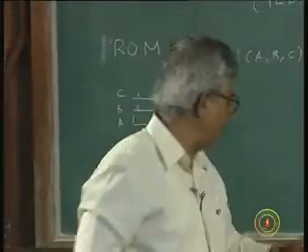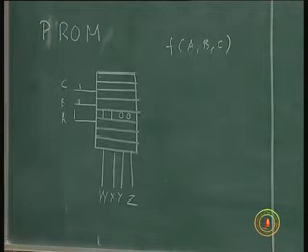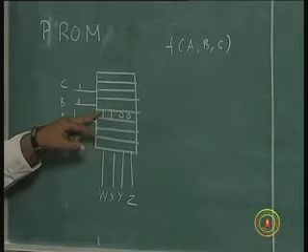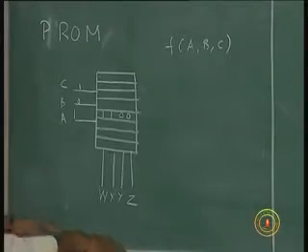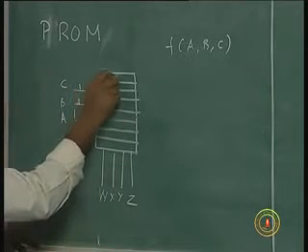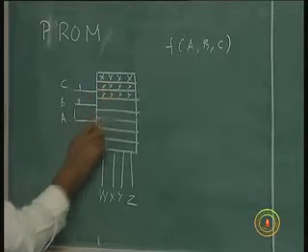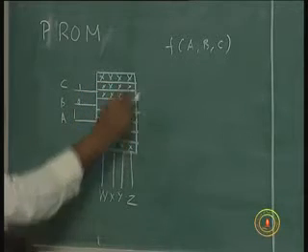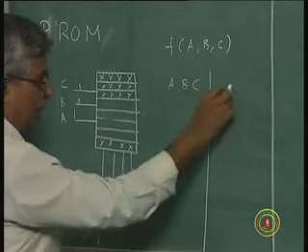So instead of making it a fixed hardwired truth table, I will add a P to it. So introduce this programmability here. I will write as required in my truth table every time the new value. That is the programming aspect of it. So instead of fixing 1100, I will have these 4 Xs which will be changed to my requirement. So I will now get a new truth table for the given application.